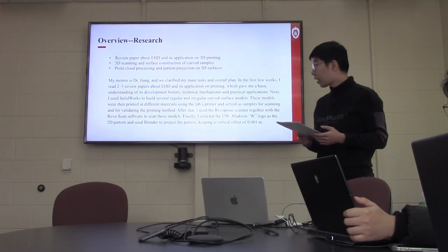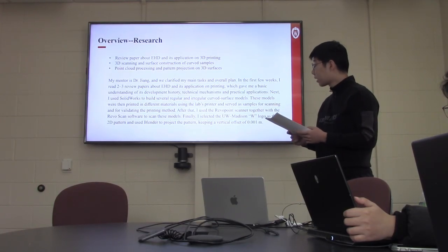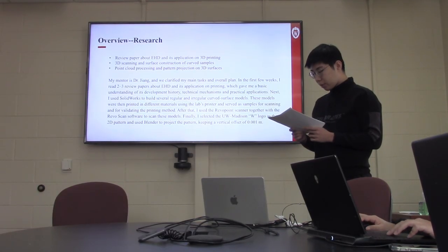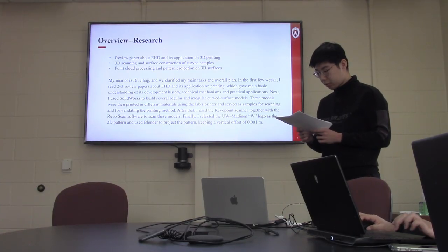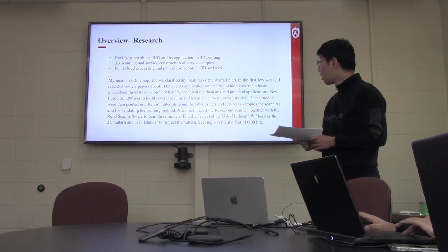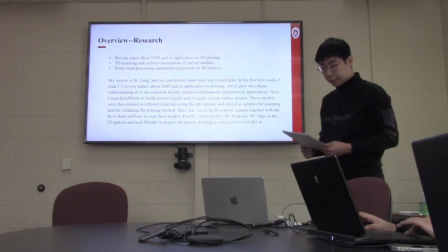Third, I did point cloud processing and pattern projection on the 3D surfaces. I generated a cloud of points from the scanner data and then mapped a flat pattern onto the curved surface defined by those points. Each of these steps was crucial. The literature reading shaped my approach, the scanning gave me the necessary data, and the pattern projection set the stage for applying our printing technique.